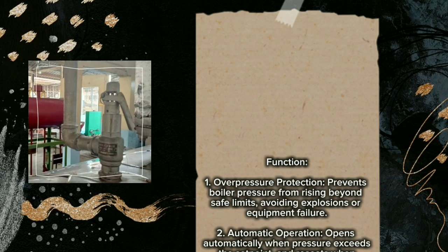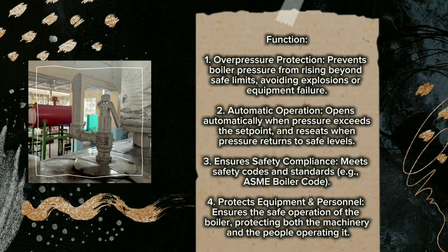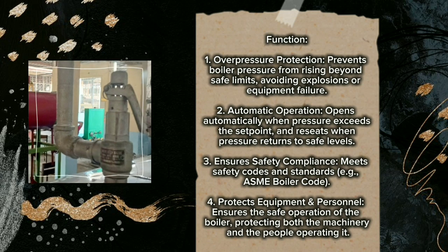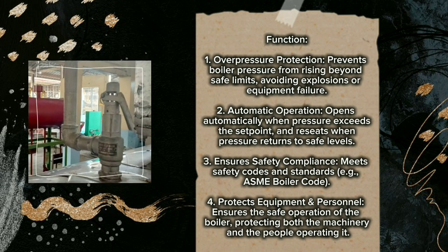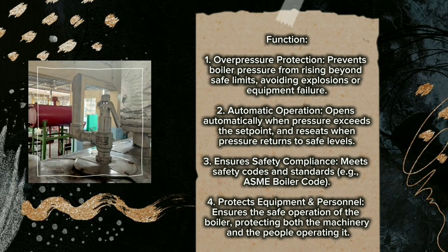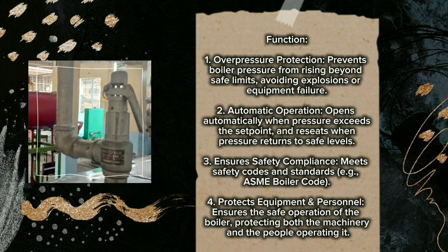For its function, number 1, overpressure protection. Prevents boiler pressure from rising beyond safe limits, avoiding explosion or equipment failure. Number 2, automatic operation. Opens automatically when pressure exceeds the set point and resets when pressure returns to safe levels.